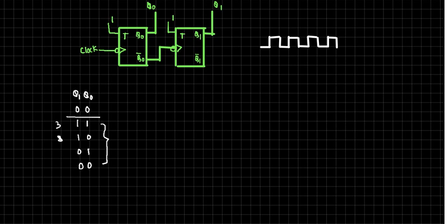So the full name of this is 2-bit binary asynchronous counter, right? Down counter, isn't it? Tell me the full name of this. But what edge? 2-bit asynchronous negative edge down counter using T flip flop. That's how you should do it; everything should be mentioned in the name.